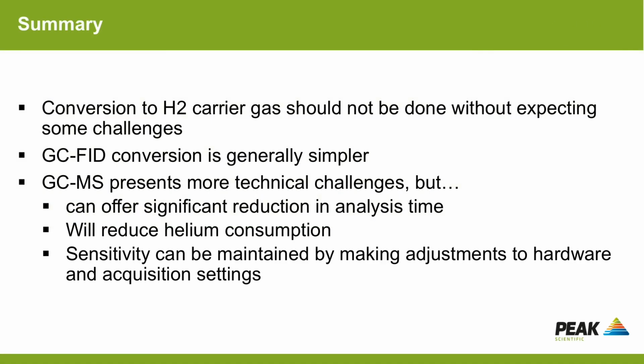To summarise what we've covered today, converting to hydrogen carrier gas should certainly not be done without expecting some challenges. Generally speaking, GCFID method conversion is simpler. Of course, there could be some difficulties involved, but generally speaking, it's easier to achieve without having to make big changes to your setup or to the method.